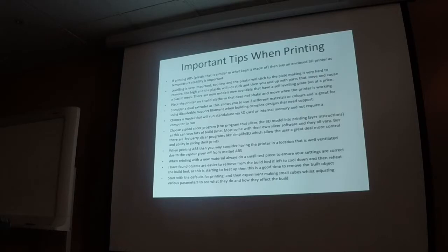So start with the defaults. When you're playing around, start with defaults for printing, then experiment, make some small cubes, and adjust various parameters to see what they do. Get to learn the printer, get to learn what it does, because all these parameters make a big difference to how the end object comes out. If you want something very functional, something a bit more solid with more structural integrity, you want to know what parameters go in to help make that happen. So it's always good to do and play with that first.